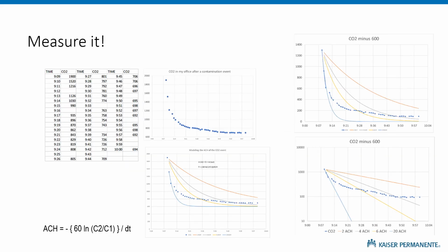I did the same thing with CO2. You can foul the space with CO2 using dry ice. You can also do jumping jacks or try the old baking soda and vinegar trick, but speaking from experience, use dry ice. It's very easy. Again, the results don't behave like the equation predicts. It starts off looking fantastic, 13 or 15 air changes, which is not true. And then it trails off to 2 to 4 air changes, which is true. That's the actual supply rate.